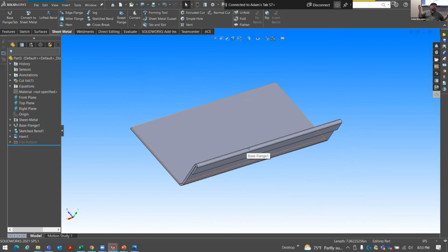Maybe you're running wire over that edge, right? Anything you want to be protected, because as soon as you shear, punch, or cut something on a sheet of metal, and especially I would say the thinner it gets, the worse it gets, you create this burr or this sharp edge that's so time consuming for your manufacturing team to remove, right? And of course, time is money, so we want to speed up that process. And if putting a hem bend on something's going to do that, let's do it. All right.